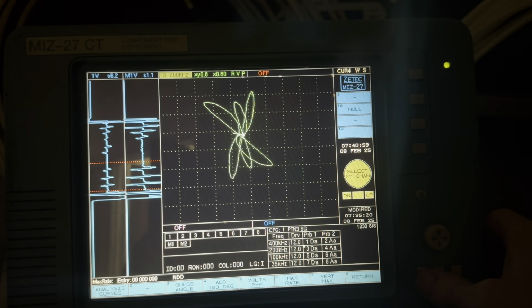So what that's saying is, hey, on this channel 3 that you're looking at, there's not a lot of phase spread in there to accurately size flaws, from 100% all the way down to 1%. That's 100, 99%, 88%, 87%, 85, 70, 60. There's a lot of percentages between 40 degrees and 180 degrees. But if you use a channel that has low phase spread like this, every degree of phase angle shift, you're going to have 2 to 3 percentage points difference.